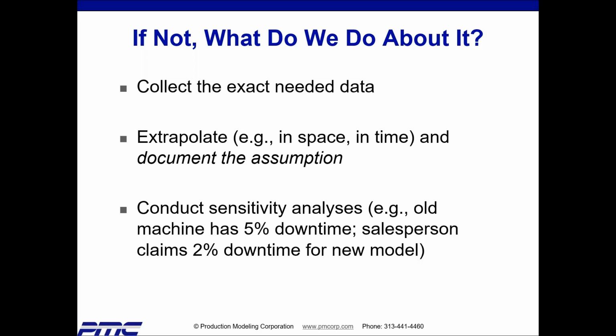So the first thing we do is conduct a sensitivity analysis. We build a model of the plant as it is now and run it to validate the model results against what we see in the plant. And that model of the plant as it is now has 5% downtime in that machine. After the verification and validation, and by the way, that's a whole other webinar, we conduct our sensitivity analysis.